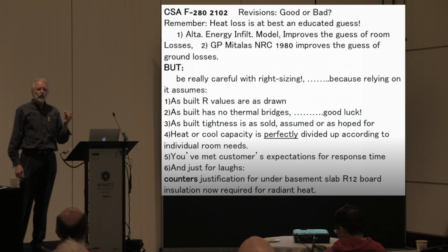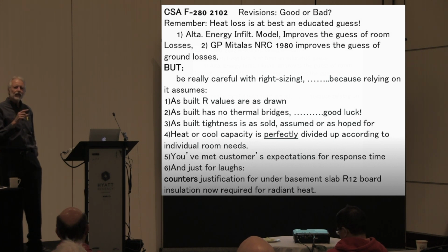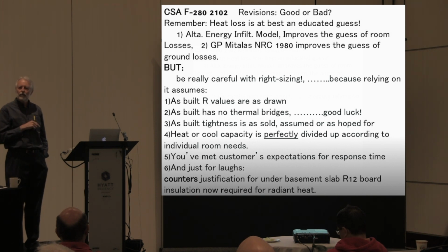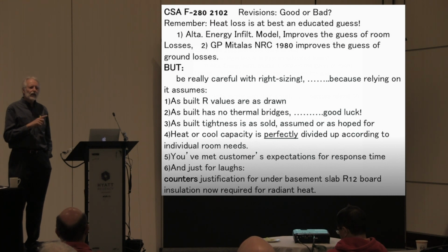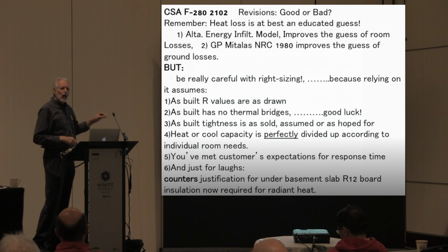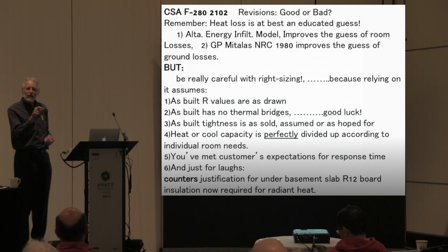But what about thermal bridges? Unless you've seen a house in an infrared camera in the middle of winter, you probably don't have a clue what thermal bridging is. I personally made a study of that because I've done indoor swimming pools for 30 years. And what happens if you've got a thermal bridge? Condensation. Anytime you see a steel post and steel beams used in an indoor swimming pool, run like hell. Thermal bridges have massive losses. And you don't insulate thermal bridges, you thermally break them, which is a different animal than insulation.